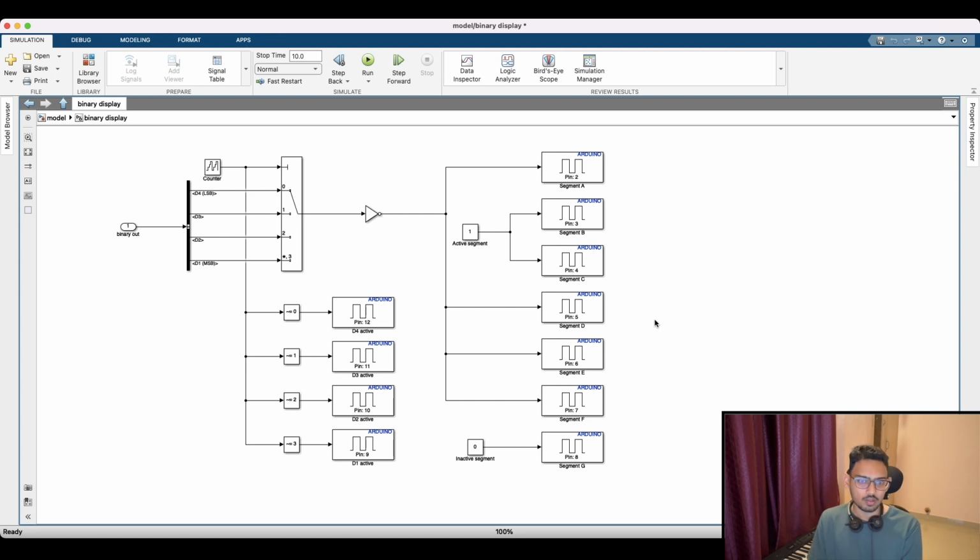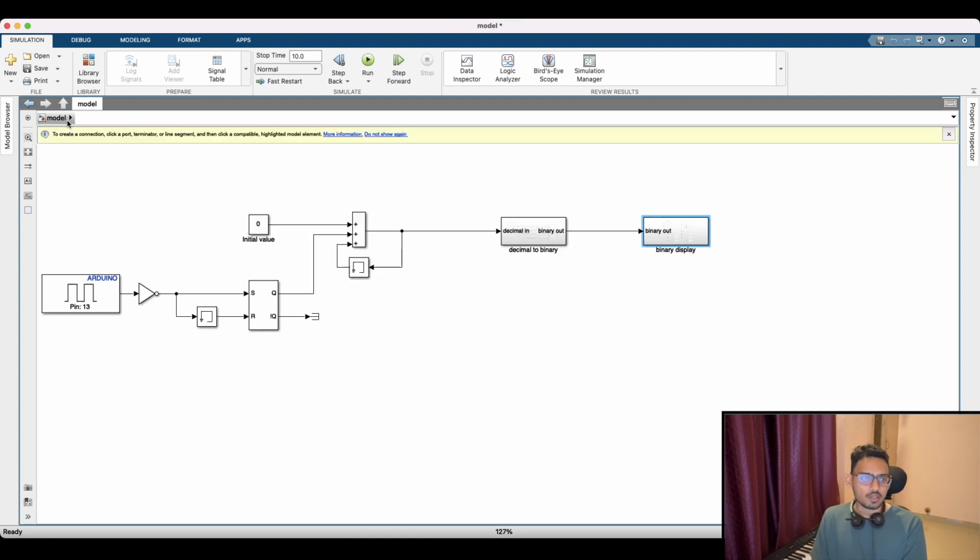So that is the overall logic for displaying this binary number. It is all because we want to reduce the pins on the display. This mux-ed logic helps us to reduce the number of pins on the hardware, thereby making the connection simple. That is all there is to this logic. Now let's see how it is actually implemented in the hardware and how it works.